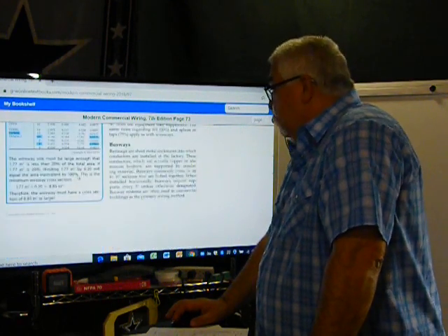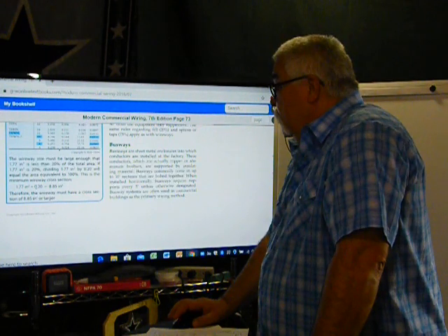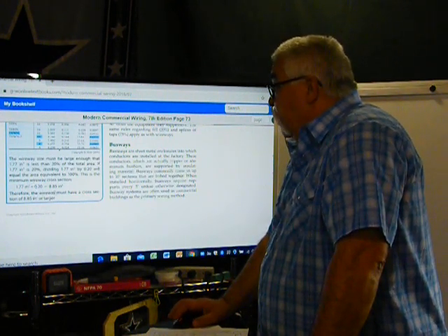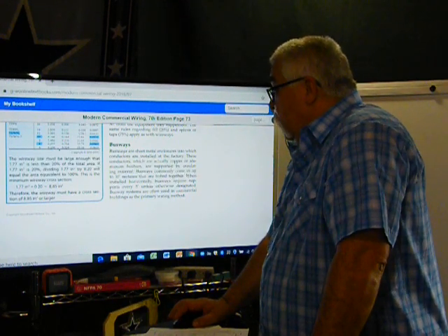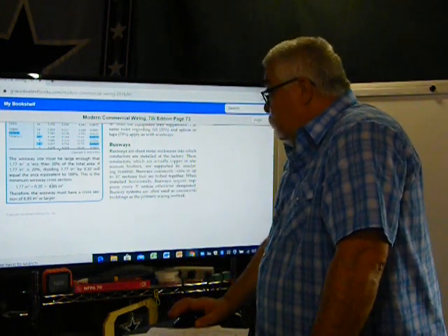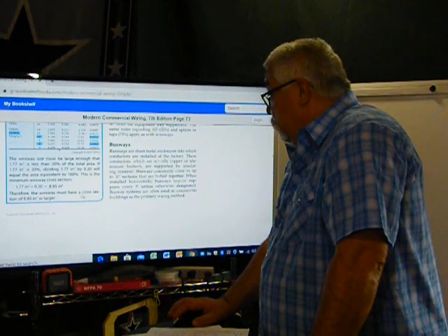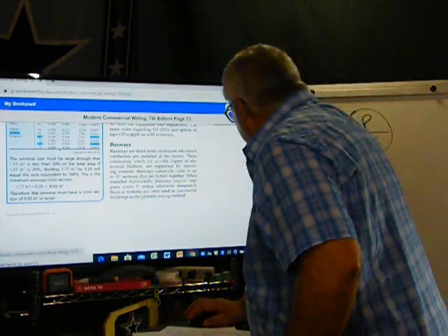It's a wireway. So we can only fill 20% of a wireway. So we're going to divide it by 20%, and we need a wireway that has 18.85 cubic inch. So therefore the wireway must have a cross section of 18.85 or larger.